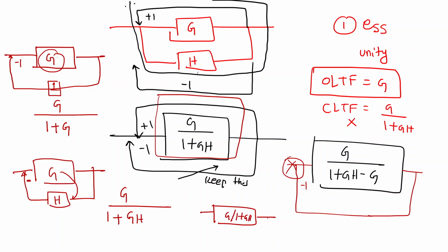And you have a positive feedback system. So what you do, first write that transfer function, G divided by 1 plus GH, and then, since this is a positive feedback system, you write minus, and whatever this denominator G is, you multiply with this. Like that I have written. If you solve using the formula, you will also get the same answer.